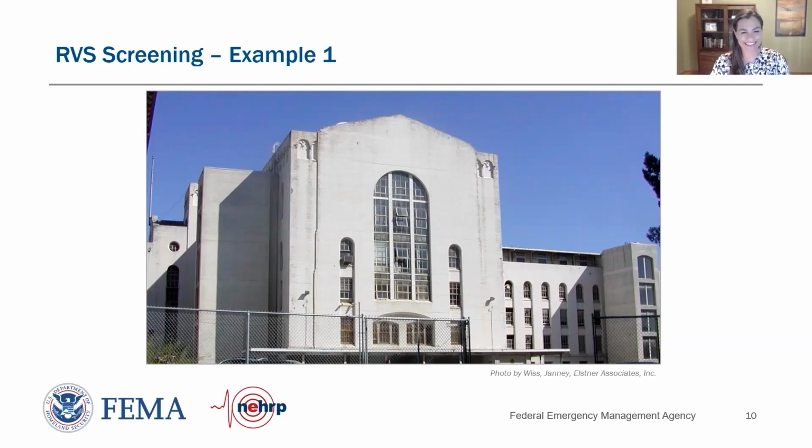And so we can get rid of wood, we can get rid of steel, we can get rid of masonry. And so we're dealing with concrete. It's not an MH, naturally. So we've got a C1 frame. We've got a C2, which is concrete shear wall. We have a C3, which is our older frame with masonry infill. And then we have PC1 and PC2. Well, PC1, it's not a big box warehouse, correct? Correct. And PC2 is frame-like.